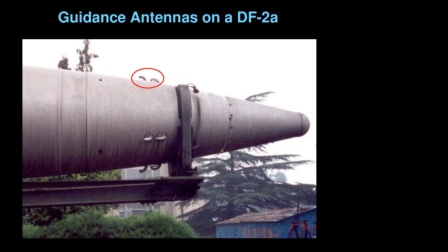So during boost phase, they'll integrate up the signals they're getting from their onboard sensors, and then at some point you want to take the error out of that, and so they can actually do star sighting, where they look for the position of a given star, and that will allow them to recalibrate their position. The other possibility is using global positioning system data.